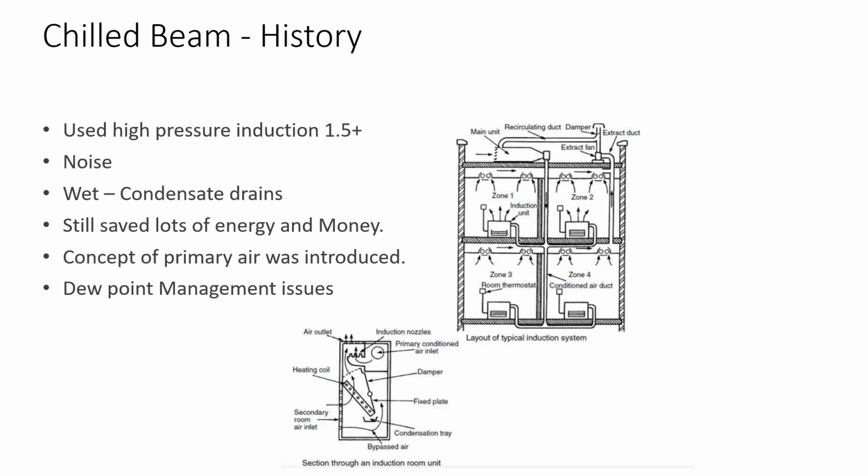And although the diagram here is a little generic, if you could see where it shows the primary air inlet going in, there's a series of nozzles there. That process pulls air from the floor across that coil, then up the top of that air outlet. So once again, it's that increased velocity that induces the air from the floor, or in the beam scenario from the space.